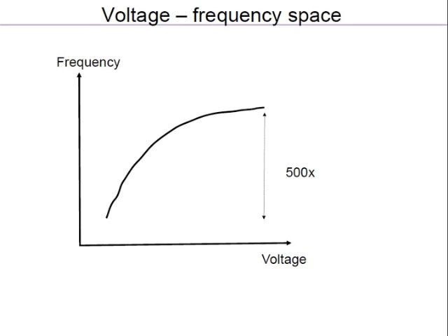Sometimes you can design circuits which don't run at slow speeds. Of course, they will not run at very high speeds for natural reasons, but it can also happen that they don't run when you run them slowly. So we will see some examples of circuits. Essentially, they have to do with leakage. The circuits are relying on information being kept dynamically, and then it gets consumed quickly. But if you are running so slowly, the information gets consumed only at a slow rate, and it can leak away. So if you use such dynamic circuits, there is also a lower bound. You can't run things too slow.